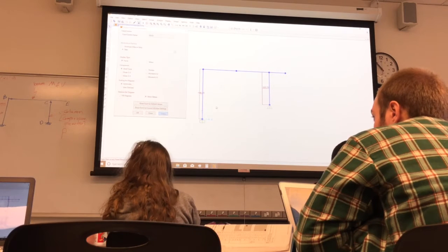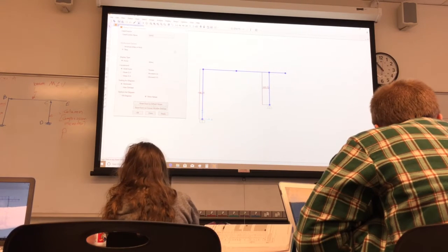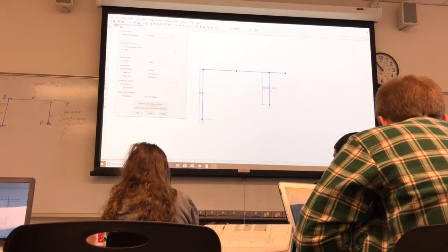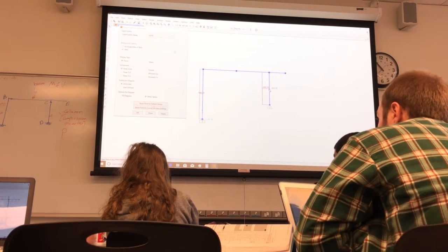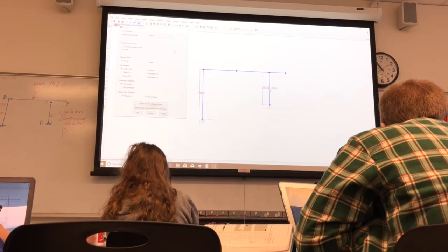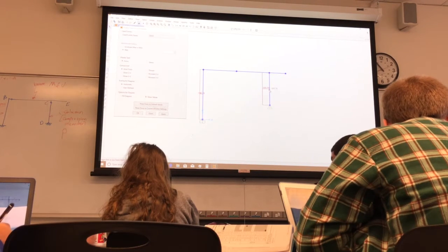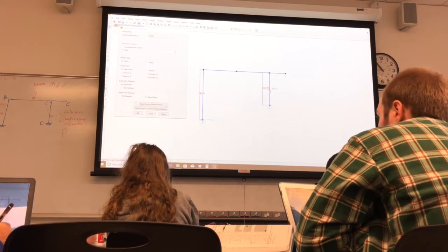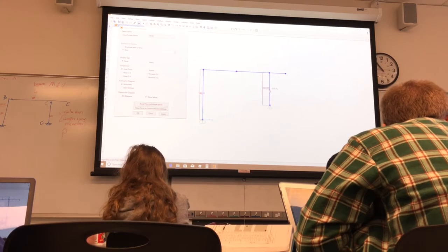So we go to the SAP model, and then we look at the axial forces for each case. Click apply. We're talking about this column here. So it's negative. You want to be careful with the units too. So it's negative dead, negative 323.75 kips. You put these in a table format.